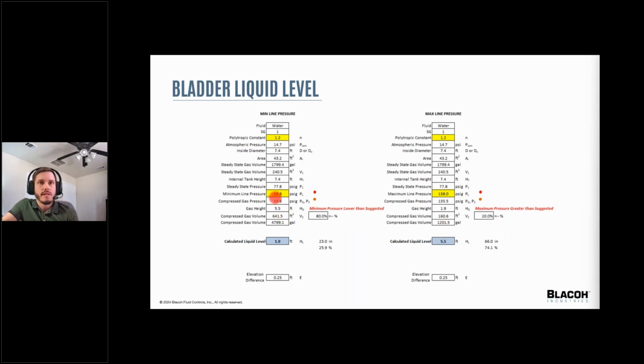at pressures less than 20 psi in potable water applications, the city may need to issue a boil water notice for unsanitary backflow concerns. And then if you go above the max pressure, our tool will flag you, of course.